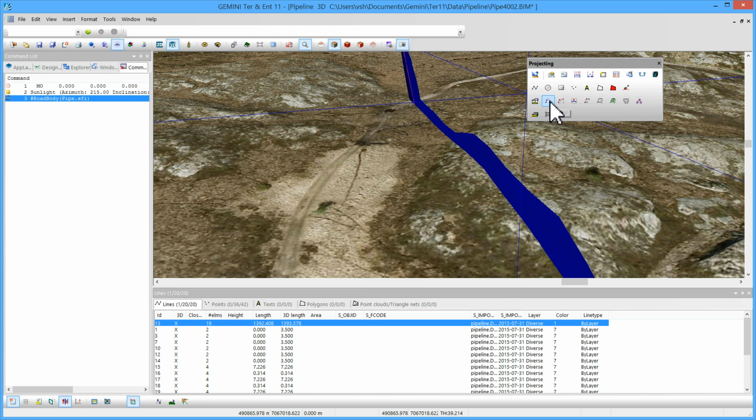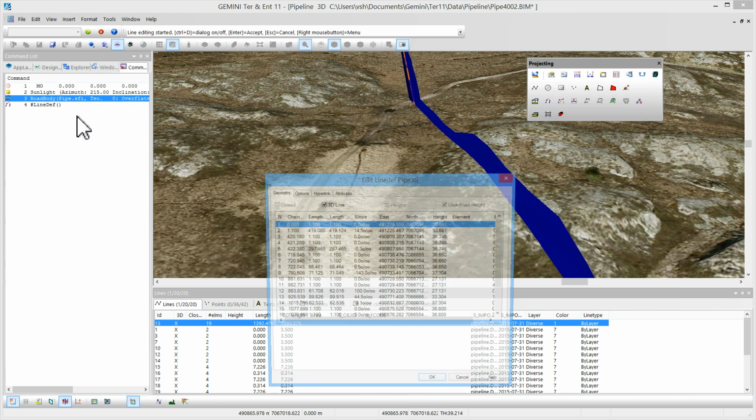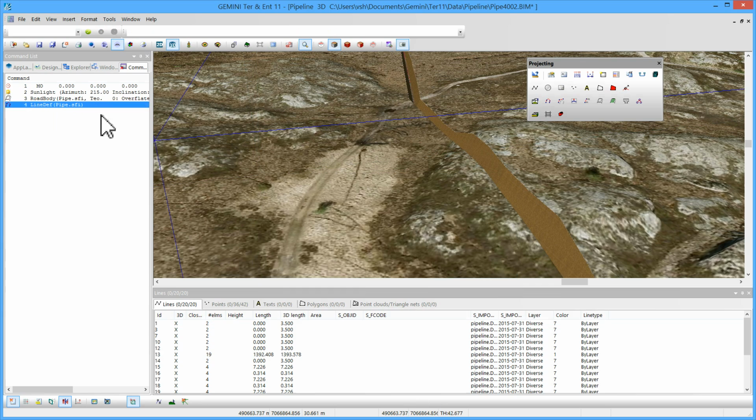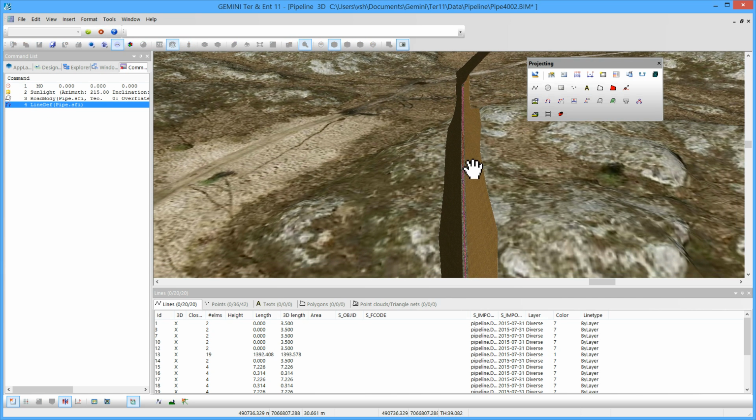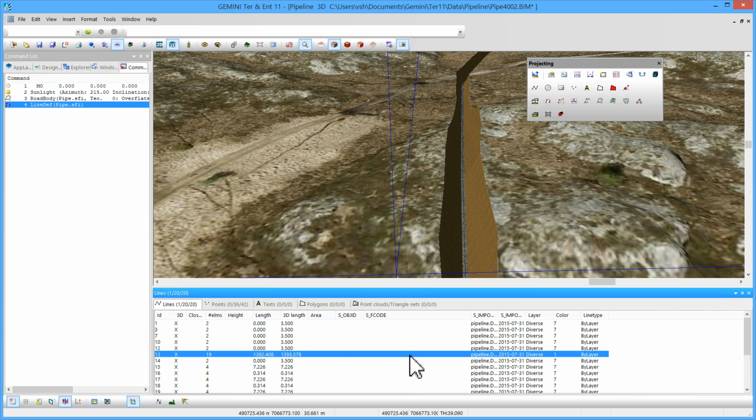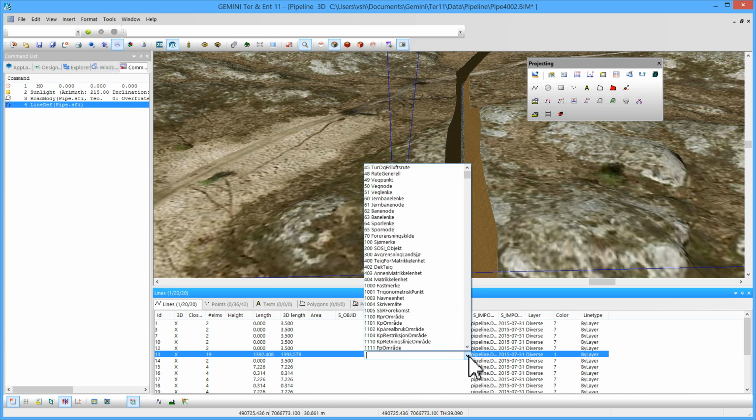I can use this button to simply insert the center line of this road. We can see that the line definition is now already here. I will modify the presentation of the original line to make it look like a pipe with arbitrary geometric properties. To do that, I use an attribute called sfcode. I use some value, for instance 8201, which is a Norwegian standard for water pipes.